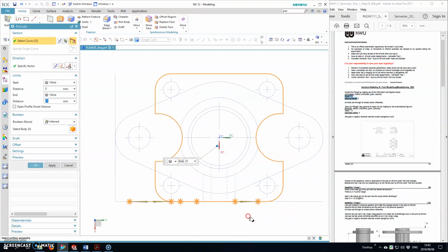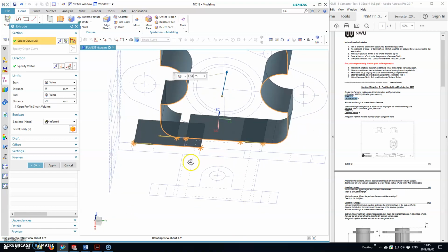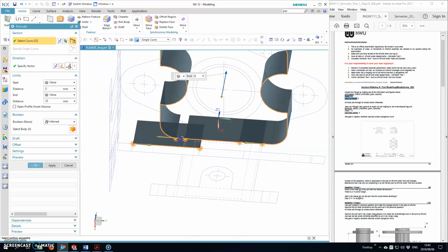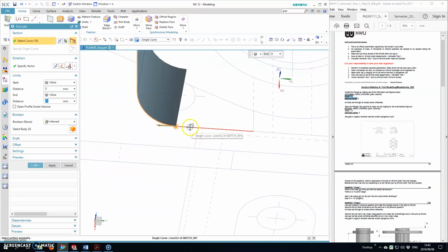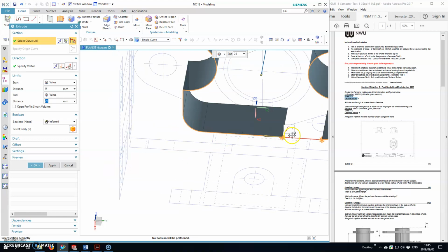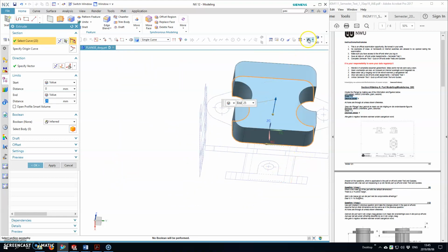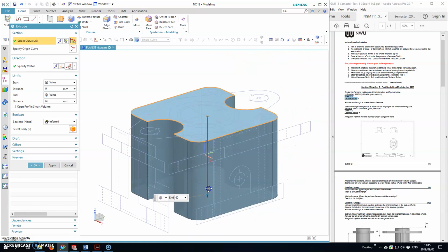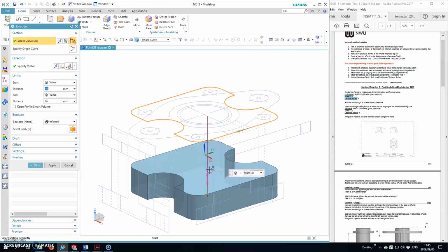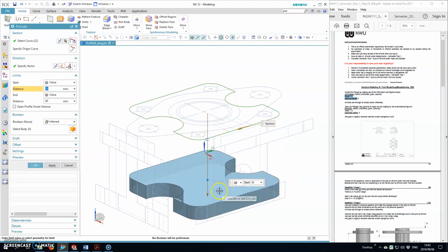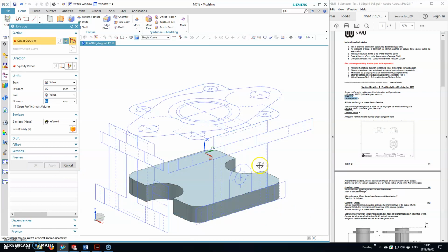Here we can see that there's some inconsistencies. This is basically because we made the wrong selection. So shift, deselect. Right now we can select it properly. So we want the direction to change. Make use of the snap to object to specify the end conditions. Okay. Apply. Next thing would be, let's change the selection filter to region and boundaries.